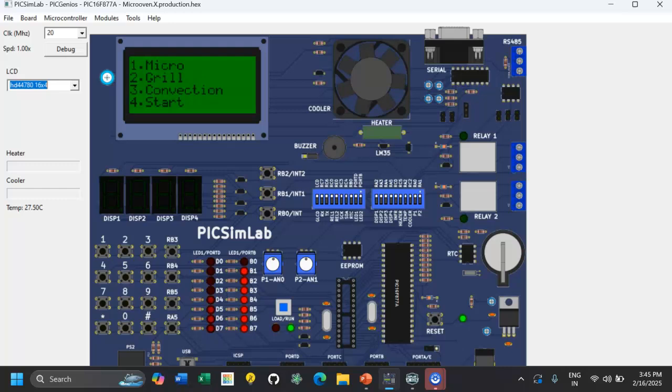We see it step by step. First is the micro mode. For that we press the key 1 on the matrix keypad. Power is 900 watt. For that we have to set the time. We set time as 50 seconds and enter by using hash key.